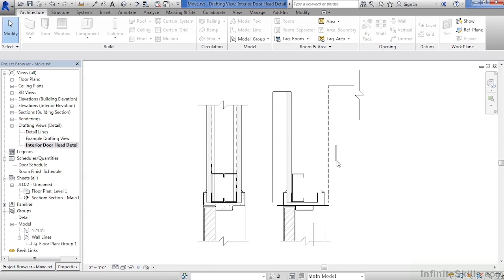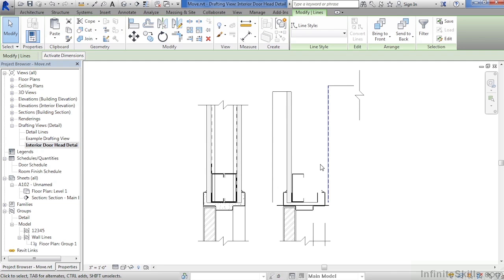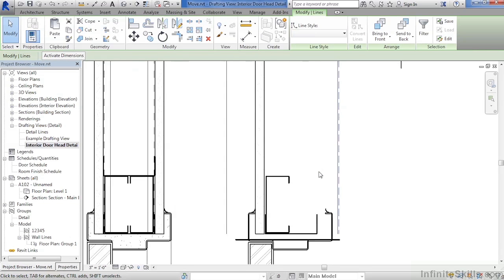So it made more sense to click over to the right-hand side, move to the left, because all we needed to do was touch these lines with the box to execute the Move command. You can now let go. These 2 lines will now be selected. You can zoom in by spinning the wheel on your mouse.